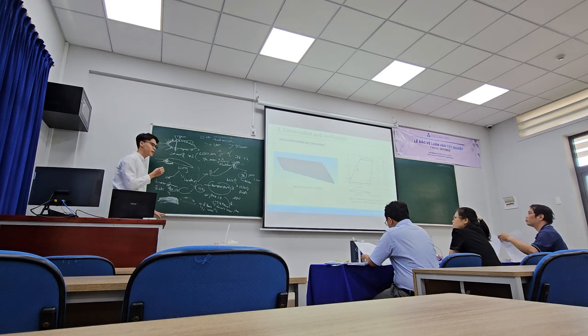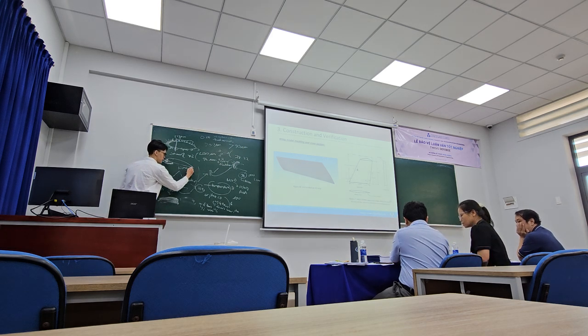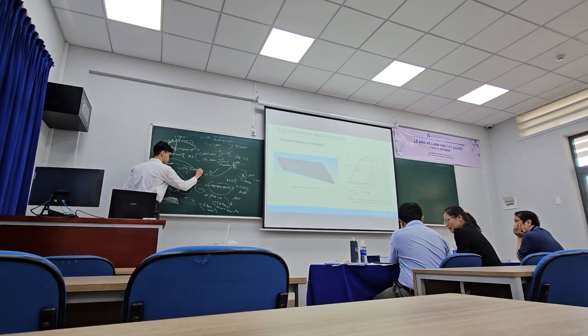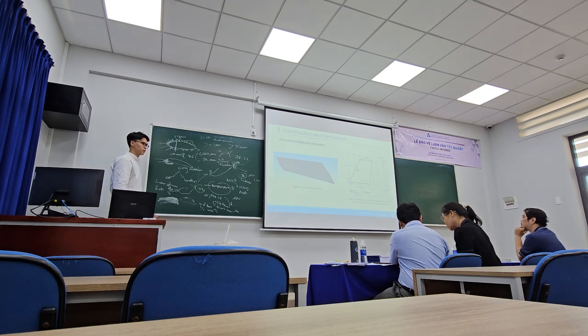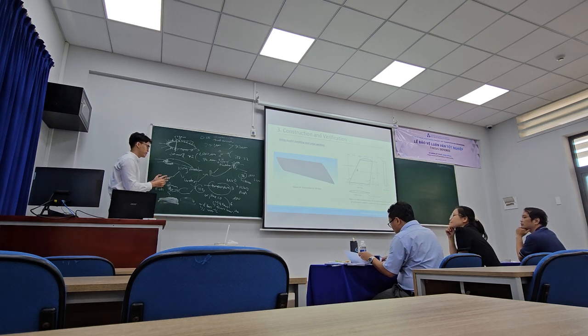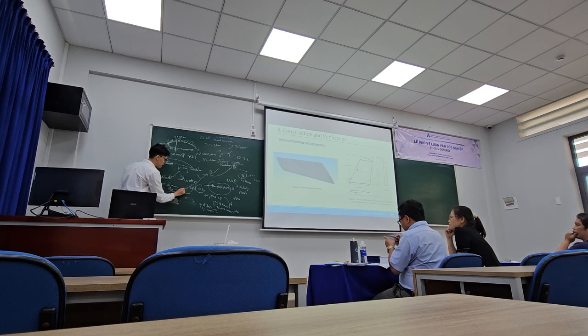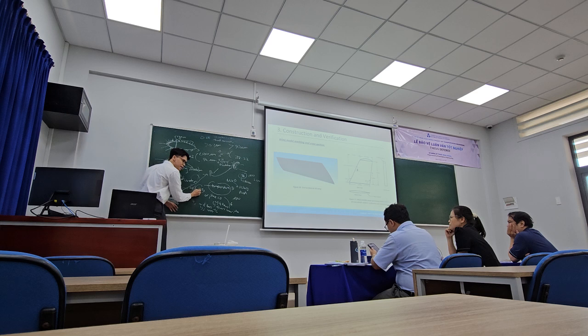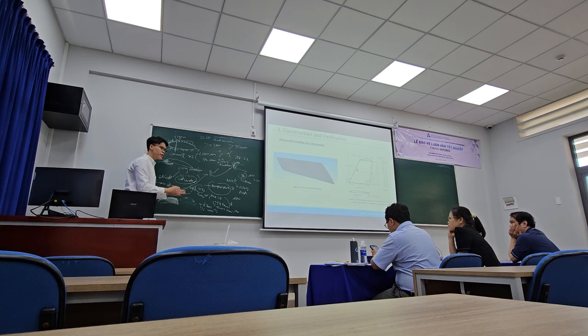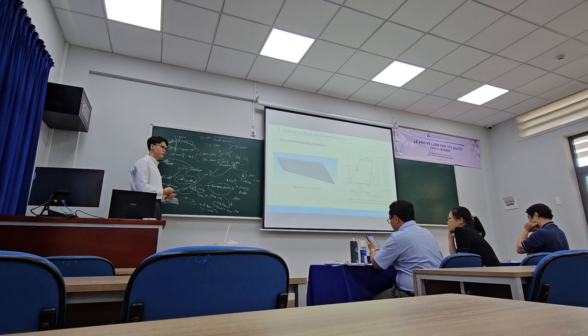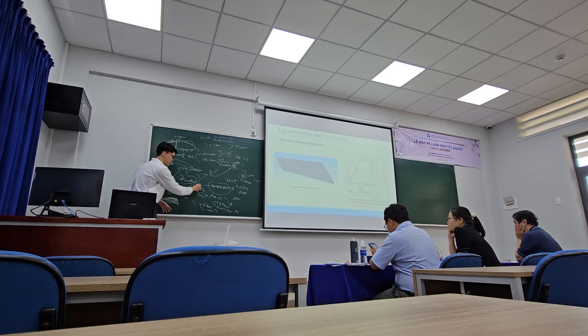Yes, but I need to make clear about the icing program. We have 3 main phases. First, we solve the air phase. Next, we solve the water phase. And finally, we solve the ice. My project stops at air and water. We do not calculate the ice or the aerodynamic parameters on the ice. We calculate it just to predict the ice shape on the airfoil, as Associate Professor reminded me before.